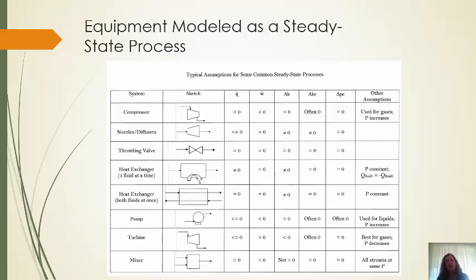Sometimes the pump, by increasing the pressure on the liquid, is going to heat the workings of the pump, the bearings primarily, so much that they are going to mechanically fail. And so what we would do in that case is add cooling to our pump. So I may have Q less than zero if I have a cooled pump.